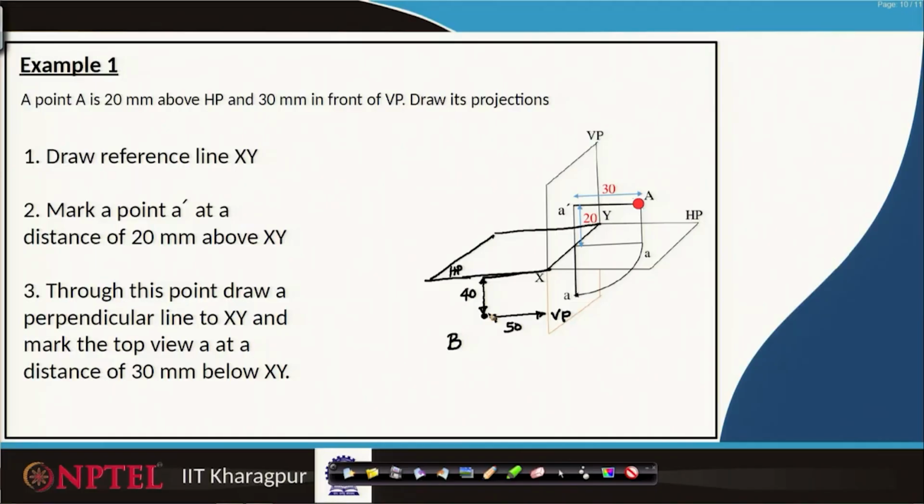For that purpose, recall our last thing. We have to project this point straight away onto the vertical plane always; somewhere it goes below. But for the horizontal plane, the way we do it for the third quadrant, we always have to rotate clockwise 90 degrees. So, first of all project there, and then transfer it by radius, rotating it there. So, there we will have this B. It comes, top and bottom switch. So, let us look at that problem.